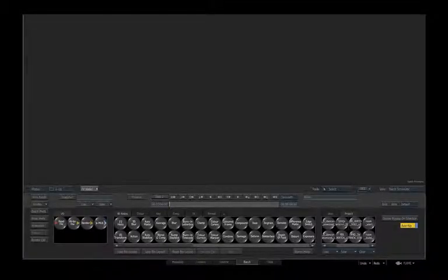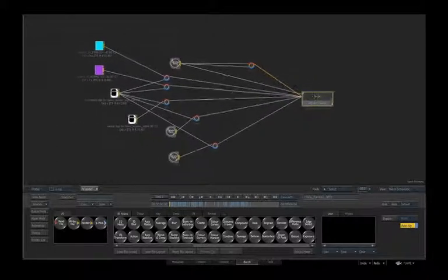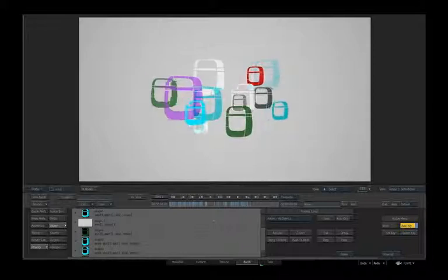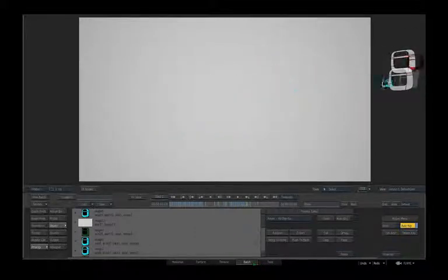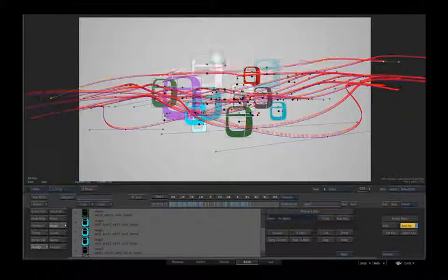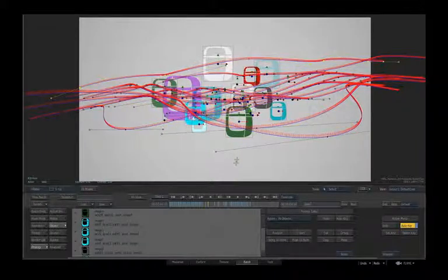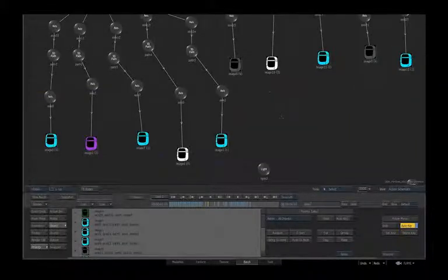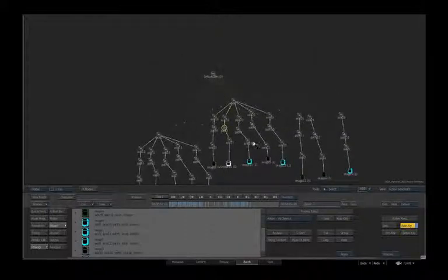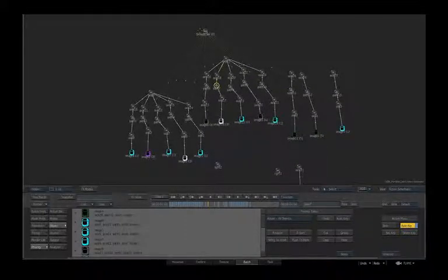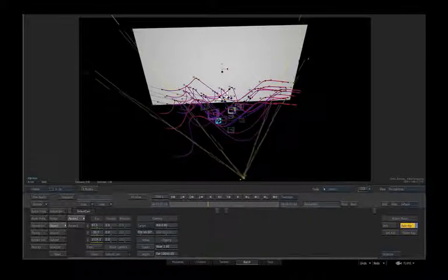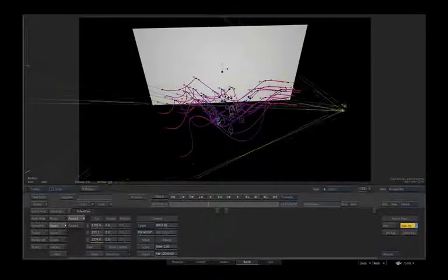We'll look in the batch environment here and start with just that background build. What we're doing here is using 3D paths, which are really just paths in space to host these elements. Something that's really cool about this from a design point of view is that you always want to see these elements facing you as the camera, and that's done by using a technique that we call look at, where they all have a relationship back to the camera here. So wherever the camera points, all of these graphic elements will face. Pretty neat way of working, keeping everything facing towards you all the time.